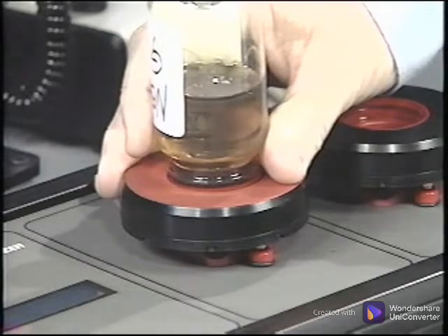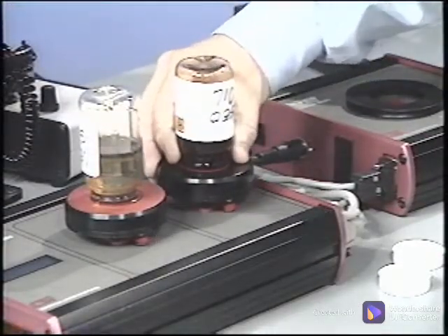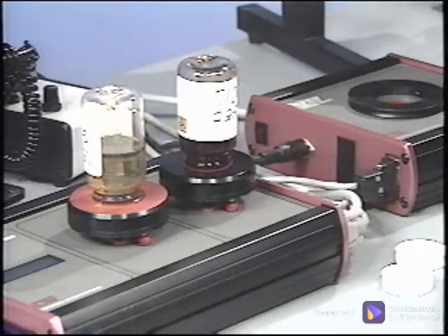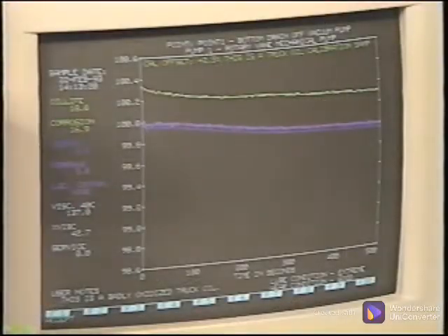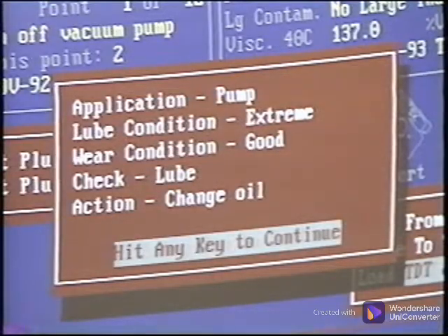After proper setup, used oil samples are well shaken and tested for 500 seconds, or about 8 minutes, comparing the results to a reference oil. The comparison of the two can be displayed graphically and is noted in the indices with recommendations reported in the automated diagnostic function.